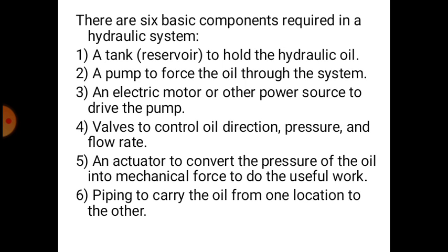So in the actuator only we are going to get the work done. After completing the work in the actuator, the oil returns back to the reservoir. Piping carries the oil from one location to the other. So we make use of pipes to move the fluid from one point to another point. So tank, pump, electric motor, valves, actuator and piping are the components of a hydraulic system.